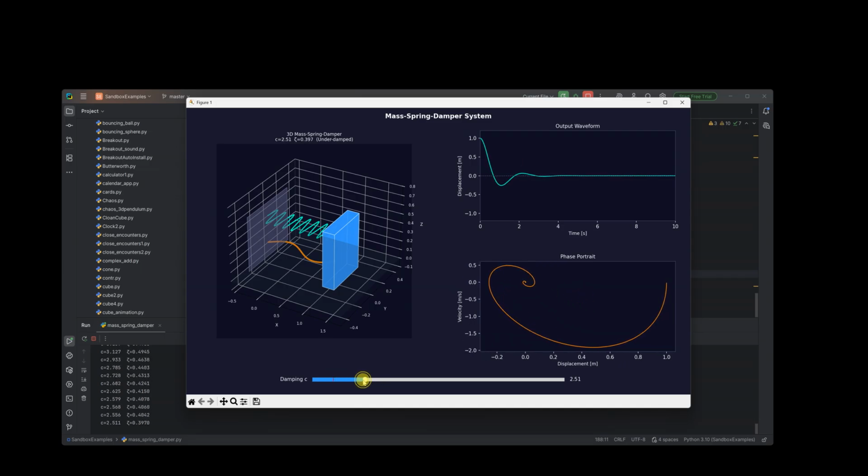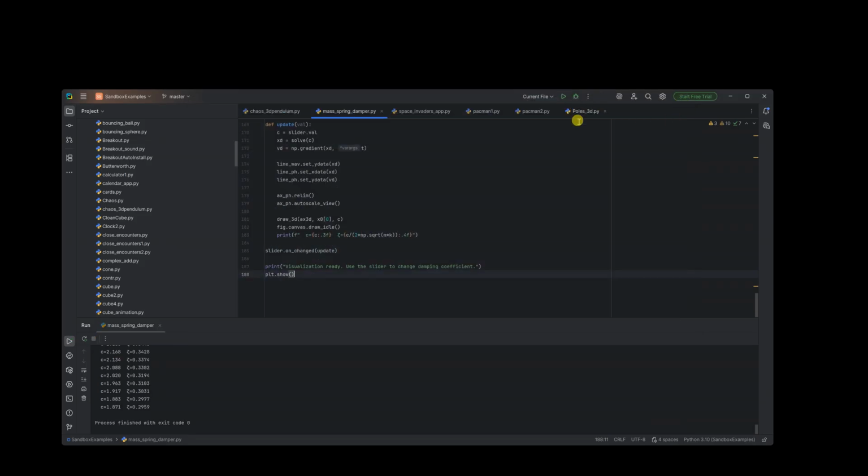Now this again here is the phase portrait. That's displacement versus velocity. What you're looking at here is what's called the equilibrium point. That's where it settles down at, which is 0. In this case, it's a linear system. In nonlinear systems, you can get more than one equilibrium point. So here it's linear. If we put a nonlinear spring in or something, then we might get some funny results and chaos and stuff. Oh, which reminds me, there's another thing to show you.